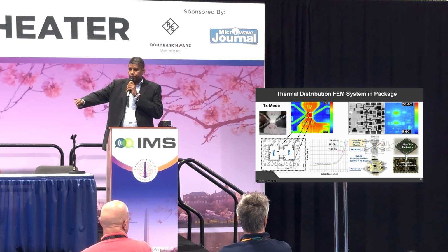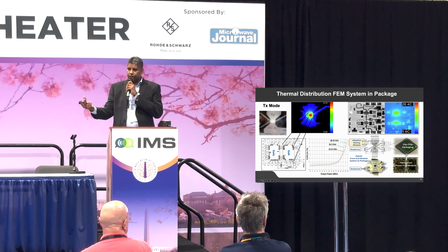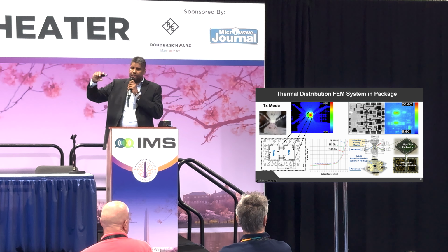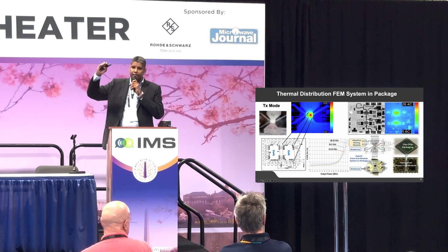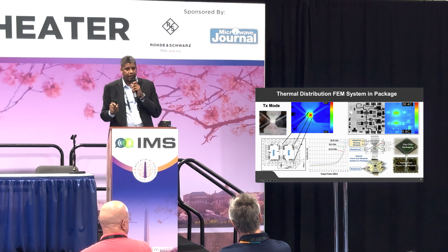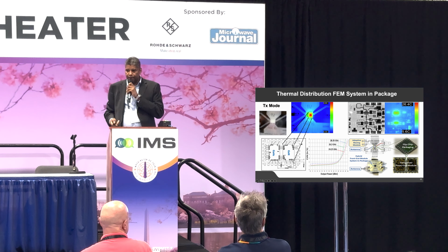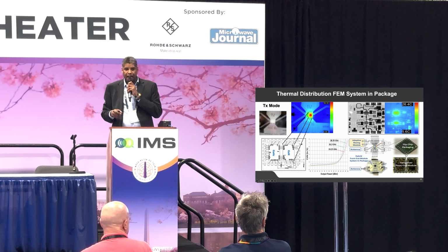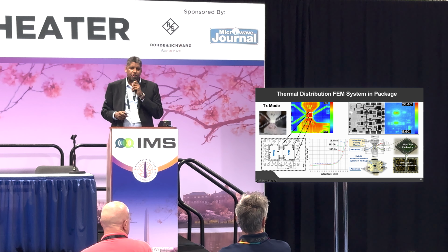On the right side, what you see is the wafer level chip scale packaging with bumps, with an RDL, a redistribution layer that is sitting between the bumps and the IC itself, and this is extremely critical. It is critical for the optimization of power dissipation, but up to now, the IR camera cannot do that type of analysis for two reasons.